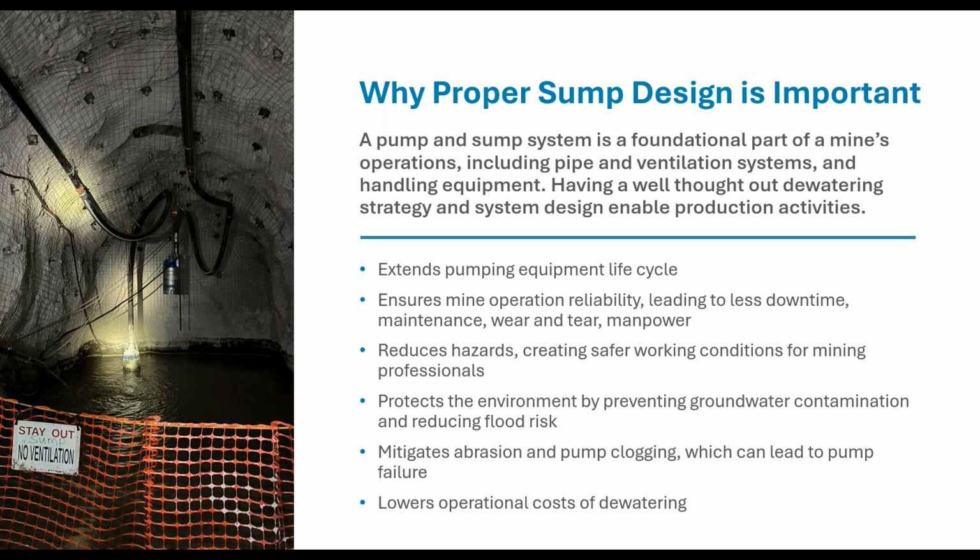When optimally designed, sumps can help extend pump life. They can help avoid clogging of pumps and reduce abrasive wear, leading to reduced performance of that pumping equipment and potentially even failure. Nobody likes to respond to a break fix situation. So we help to avoid the need for emergency response call outs late at night. Nobody likes that call after midnight that the pump is down and we need something fast.